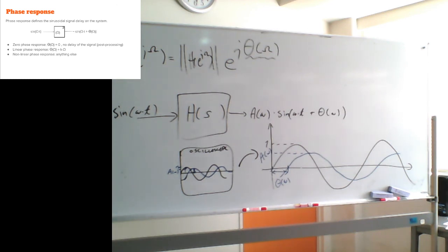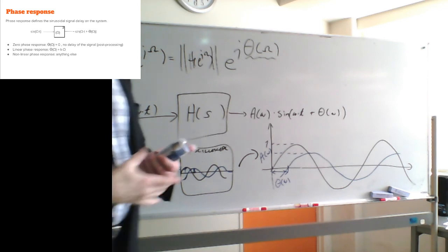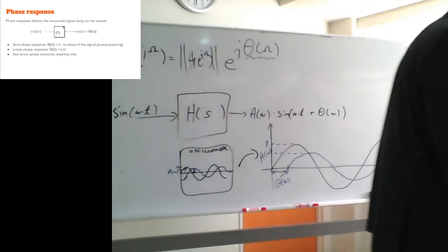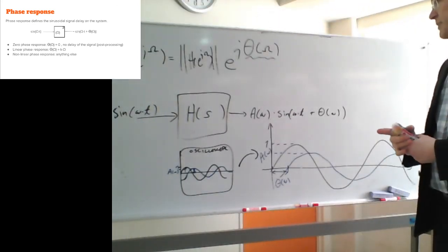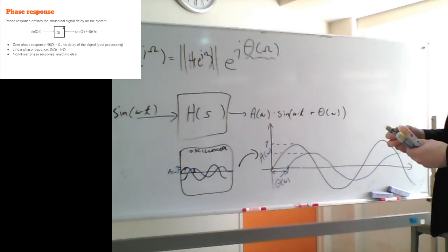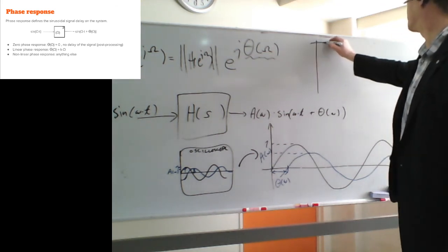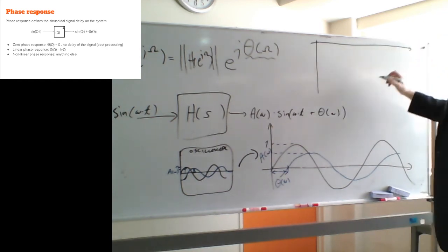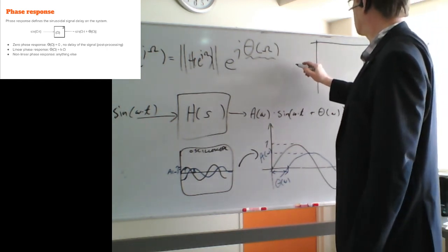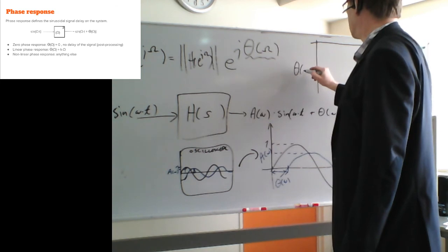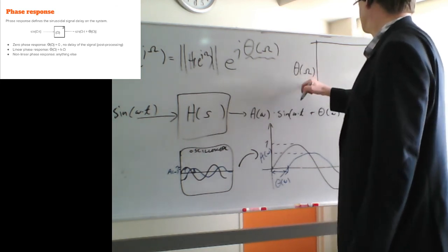Okay, but any other system, and these would be the real-time systems. That's only for post-processing. So the linear phase response is something that we usually prefer. Let me mark it on the same. So talking about linear, the phase response as a function of the omega.